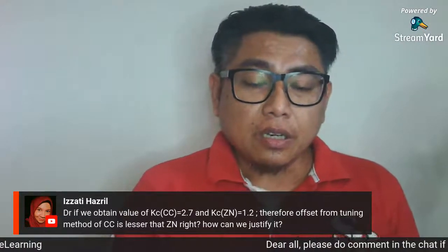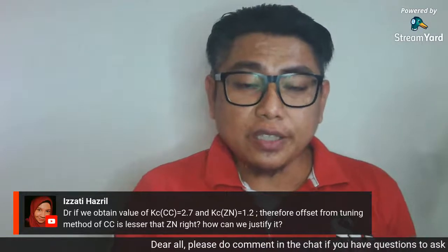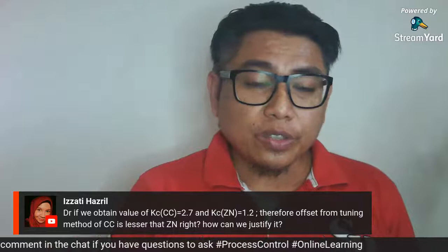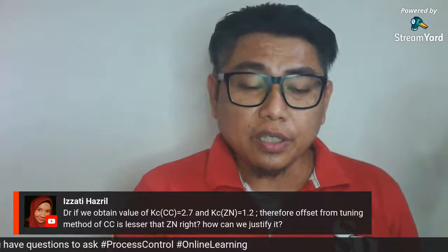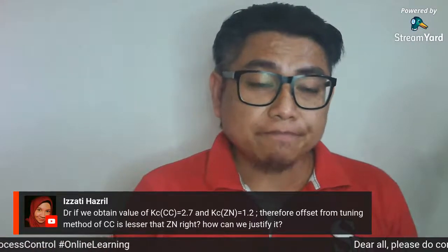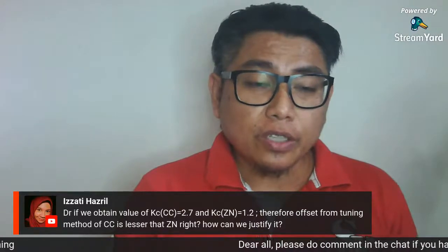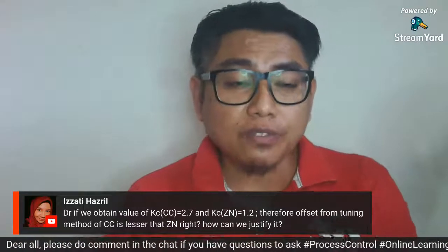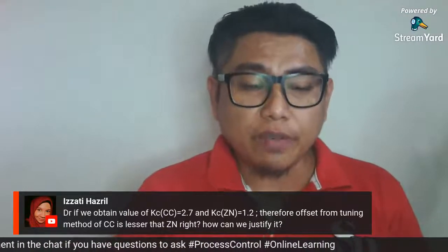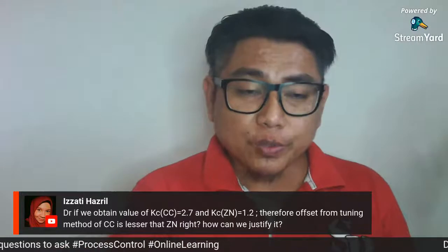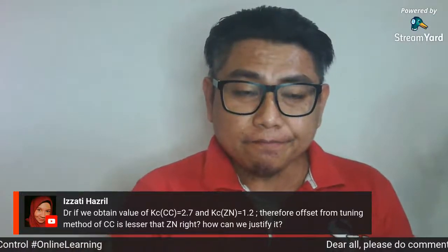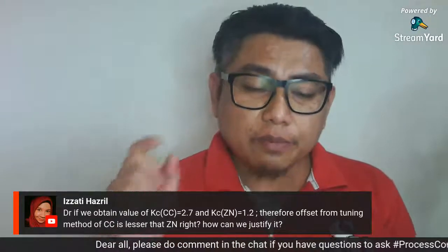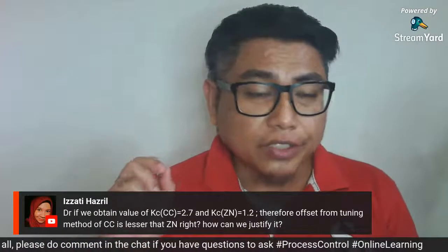You cannot justify that it is because the Cohen-Coon Kc value is bigger than the Ziegler-Nichols Kc value, therefore Cohen-Coon is better. Okay, you cannot justify something like that. You need to justify it based on the offset value. Of course, if you have a bigger Kc value, you will have a smaller offset. But in your answer, you need to justify based on offset, not based on the Kc value.